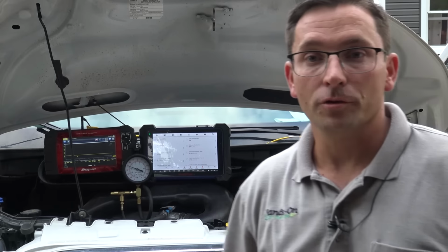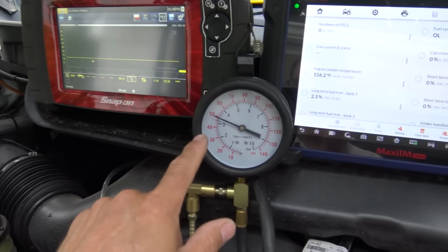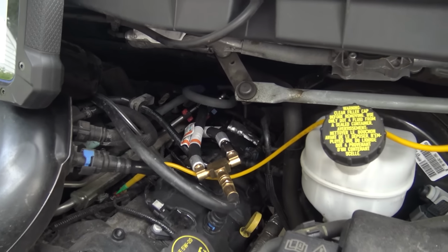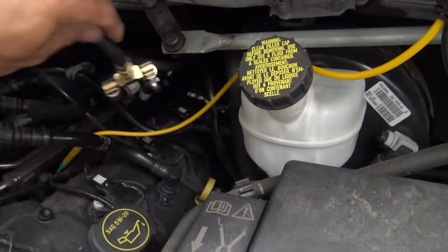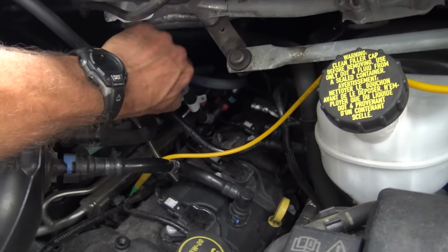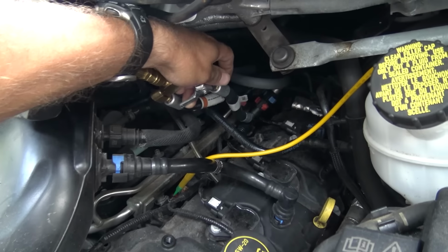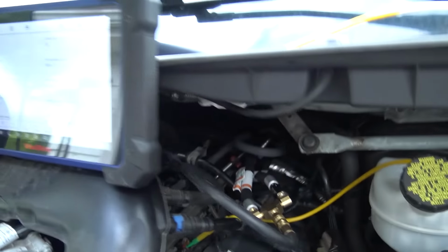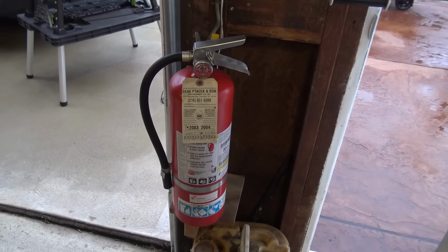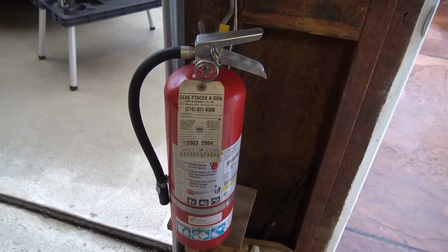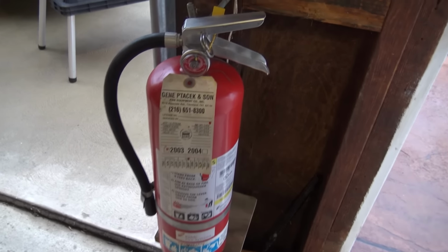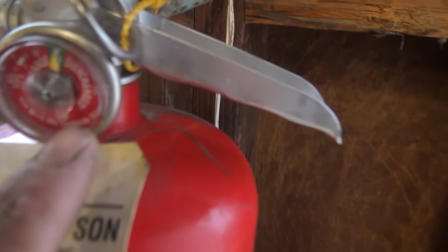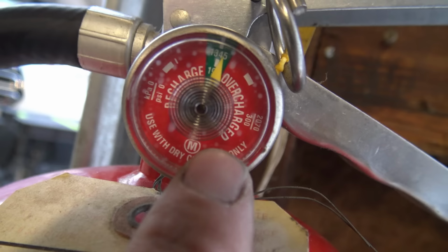All right, everybody, I want to show you our setup for this live demonstration here. Here we can see that we have a fuel pressure gauge hooked up, and this is in line to our fuel rail down there. Now on this setup, I do have a valve that I can turn on and off. This would be off all the way, and this would be on, so I can actually block pressure to our fuel rail. Anytime we're dealing with any fuel, disconnecting a fuel system or anything, or even in our shop in general, we should always have a fire extinguisher. You always want to make sure your dial is in the green there. That is the important part.